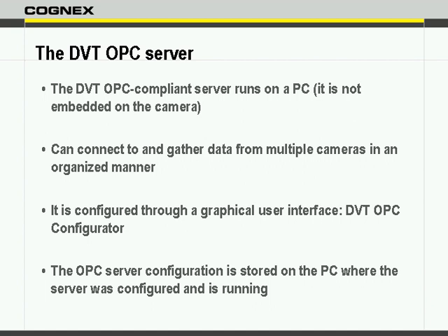The server is not always running continuously. What will happen is the OPC configurator will create all the settings for the server, and the server will start automatically upon any OPC client connection. So if there is any client on the network that is trying to access it, the server will start up and make the connection.